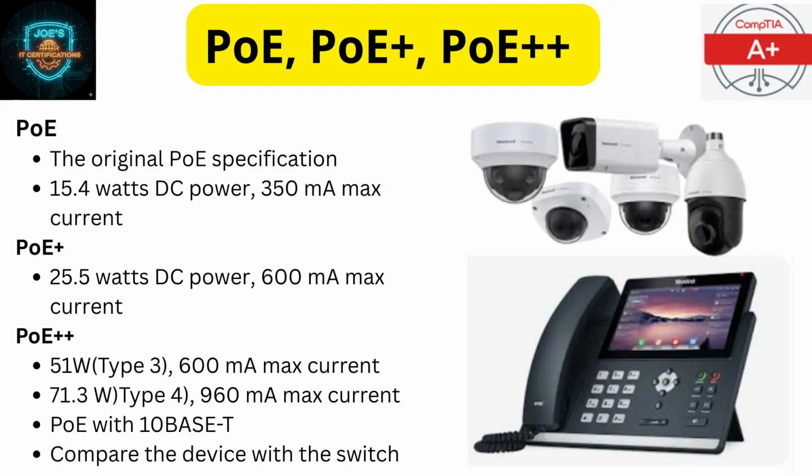With PoE Plus, we can connect larger devices that require a bit more power, things like a pan, tilt, and zoom camera, for example. And these days, we can use PoE to even power our laptops with PoE++. That's 51 watts at 600 milliamps current, or 71.3 watts with 960 milliamps current, depending on the capabilities of your switch. PoE++ is the version that was introduced with 10 gig Ethernet running over copper cables.